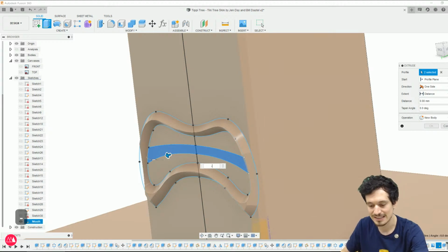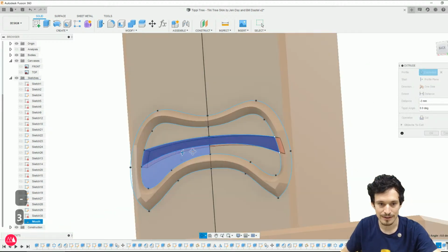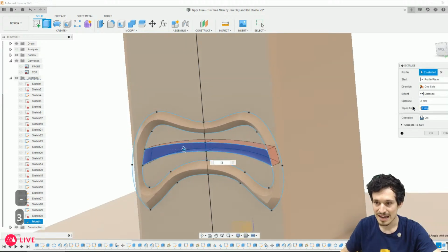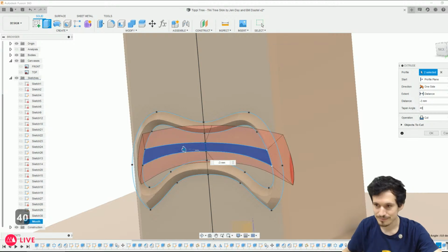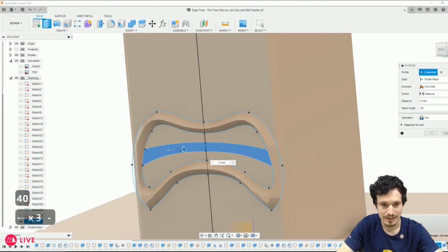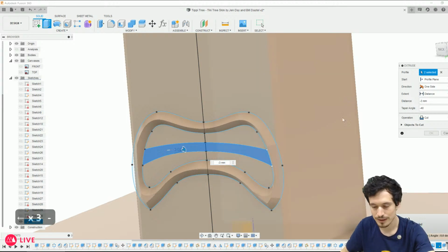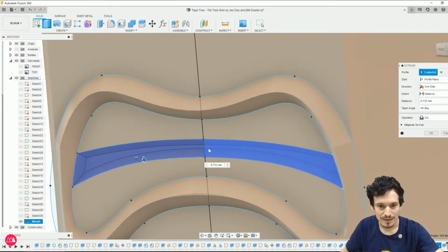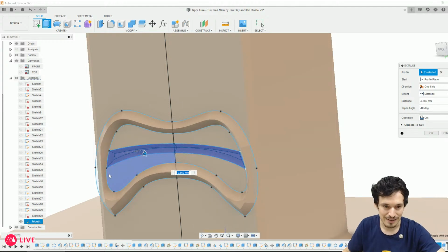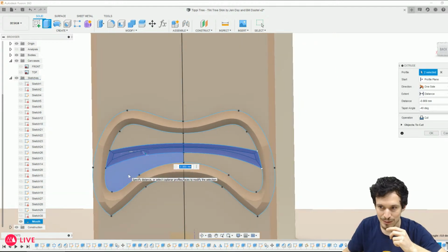So here we go. Let's do a -3, but in reality I'm just going to taper it all the way. And if I do the same taper angle as the mouth, which was 40, correct? I have to do -40. Oh no, it didn't work. Let's see what happens. Ah, yeah. Sometimes when the smallest gap meets, if you go any further than that, you'll break the extrude cut. There's ways around this, but let's just see what's going on first.